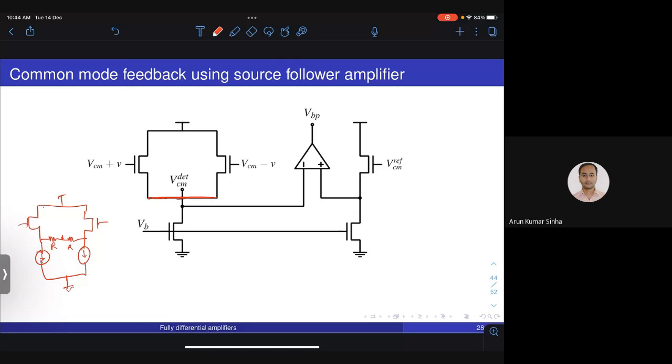So basically what happens is, if I look at this source follower amplifier, I can represent it as an amplifier with a gain of almost equal to 1, followed by output impedance of 1 by GM. Similarly, the second stage, this right side amplifier, can be represented as an amplifier with a gain of almost 1, followed by a resistance of 1 by GM.